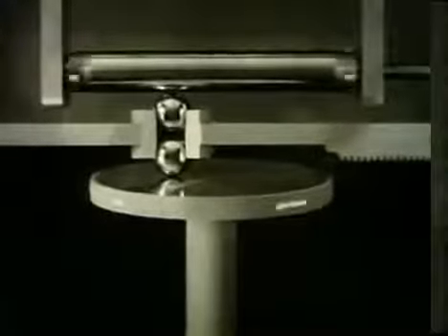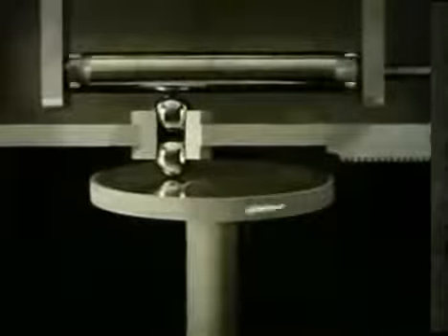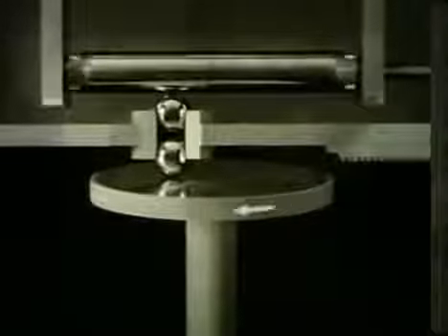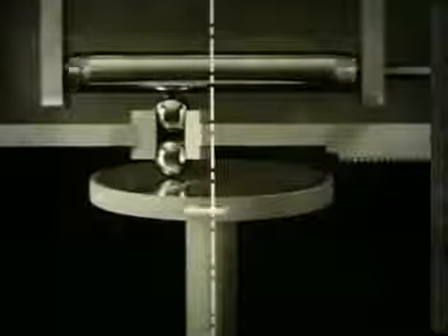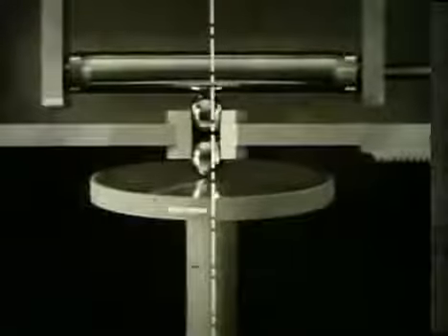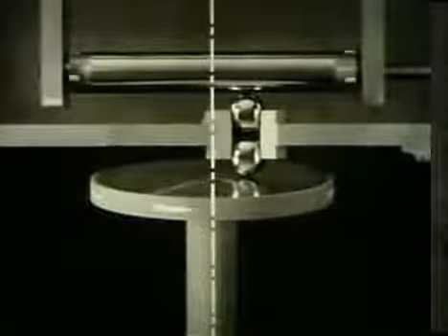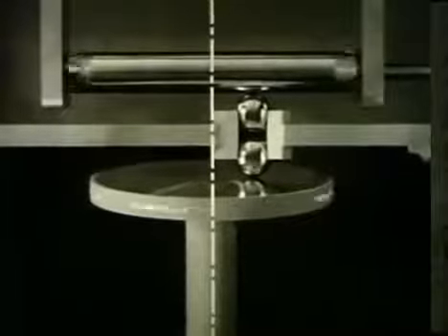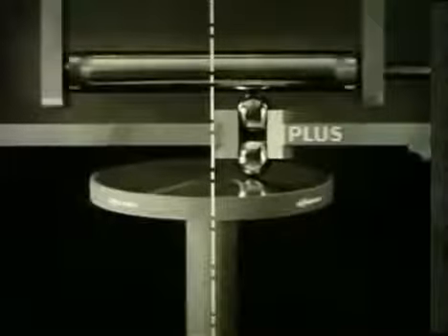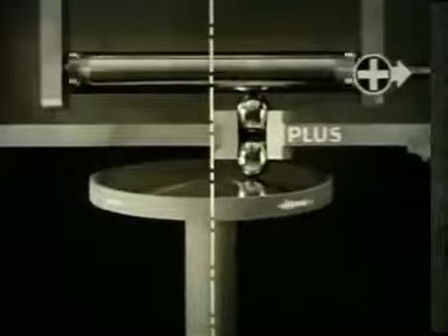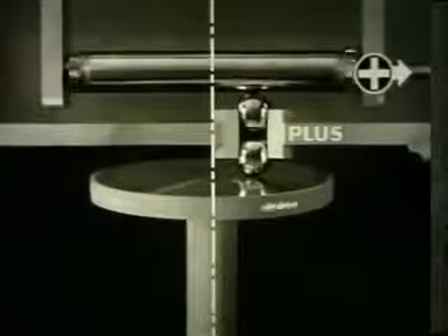There's one more point. The roller turns in one direction when the balls are this side of disc center, and in the opposite direction when they are on this side. One side is designated for plus range rates, with the output adding range change to initial range.